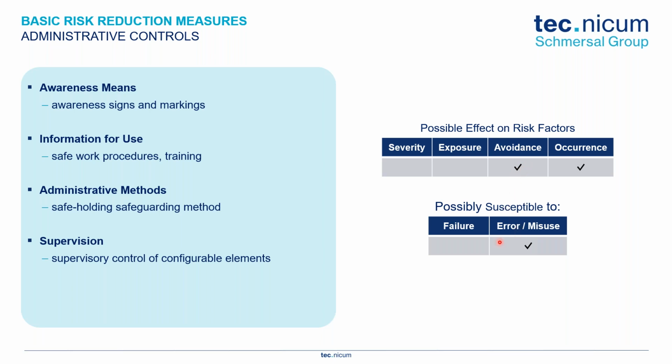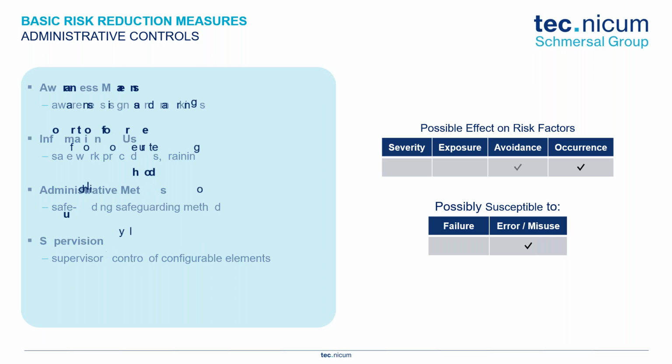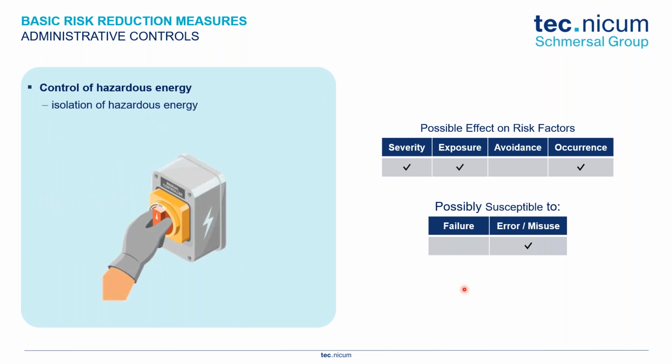And as you would imagine, looking at these administrative controls, this is highly prone for misuse and error. We are not looking at safety functions that would fail to safe. We're relying on process, training procedures for individuals to make sure that they are properly implementing these control measures. And this is why we just can't jump to this.